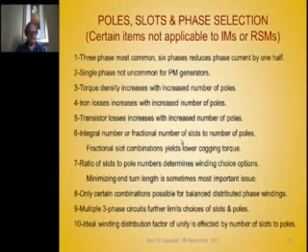Some of this is repeated from the last slide, but there's more detail on this one. Now, for permanent magnet generators, it's not uncommon to have a single phase or 2 phases. It's not necessary to have 3 phases if you're going to rectify the output anyway and use capacitors to smooth out the variation in the voltage to make it a smooth DC.